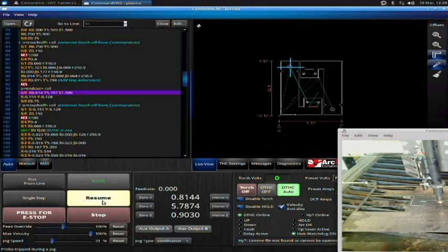Machine does the cut. Okay? So I pause the machine. I'm going to take the opportunity to repeat this process of a misfire on the next cut. Oh, as a caveat, you can hear the air blowing after the cut. It will blow for a predetermined period of time. Okay? And that is designed to cool the electrode. We can't change that airflow.